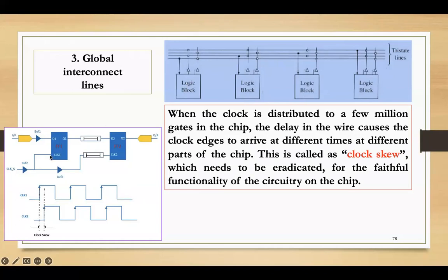Here we're just talking of 2 flip-flops, but imagine the latest processor, which has billions and billions of transistors. You can imagine the clock tree synthesis and the static timing analysis. Whenever you provide input at a particular instant, you should be able to receive it. But practically that's not possible, because it's a huge circuit and the signal has to pass through all those logical elements. So there is going to be a considerable amount of delay, and that is nothing but called skew.